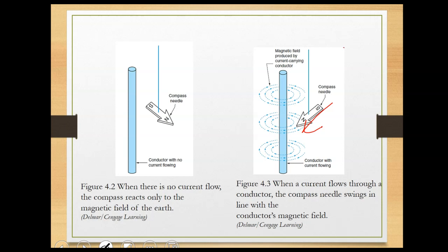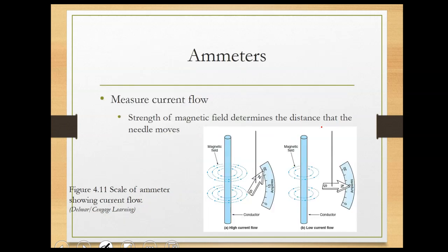You can also think that if you detect a small voltage, it's really hard to measure that little magnetic field around it. Ammeters: till this day, the main way to measure amperage is by using this magnetic field. You can measure small amperage by putting a multimeter, after you set it on amperage, in series with the circuit. Remember that ammeters are connected in series with the circuit, and voltmeters are connected in parallel with the circuit.